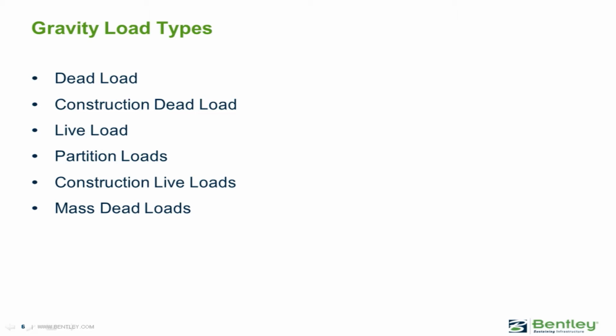Finally, you'll also define your mass dead load, and this will be used to calculate your seismic loads in RAM Frame. Typically, this would be the dead load of the structure, superimposed dead load, plus a percentage of the live load if required by your local building code.